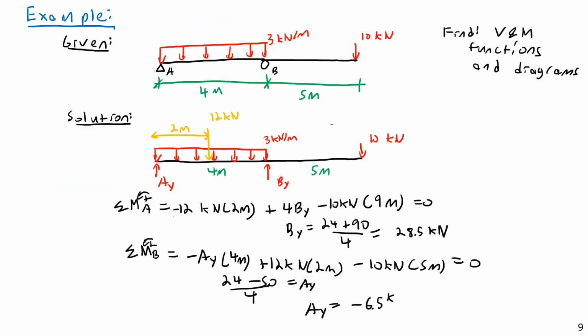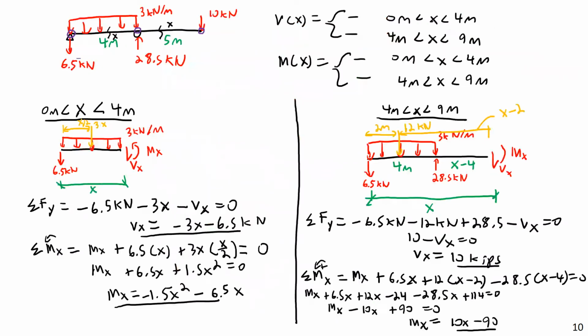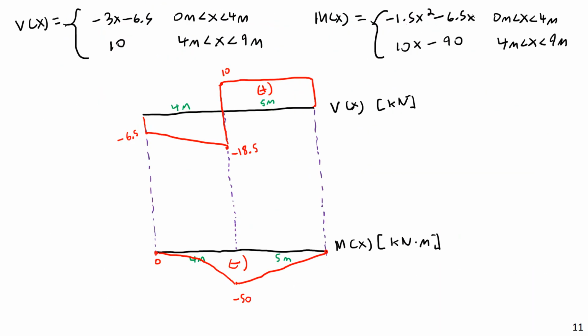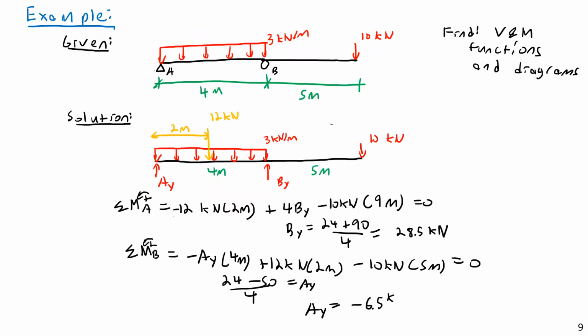Now, this is still much, much simpler than the more complex things you can see for these. I do teach shear and bending moment diagrams in structural analysis, and the ones I give those students are far beyond what I give students in this class, especially on exams. But for students in the current semester, make sure you're at least able to work through the very basics of these types of things, know how to handle discontinuities, know how to break things into zones of analysis, and know how to use equivalent point load methods applied at centroids to solve for the shear and moment in different zones by a balance of forces and a balance of moments.